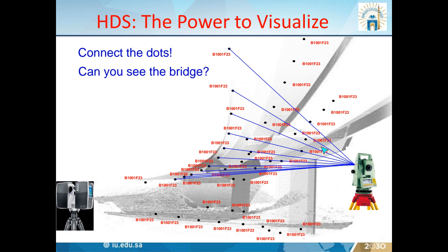And here it is showing how we get the laser points for a bridge. We need maybe 100 or 50 points to actually measure the complete layout of the bridge. So this is a normal theodolite or total station we use to get the distances or locations of the bridge, and finally we can draw the points on our drawings. But in the case of a laser scanner, we can capture it very easily.